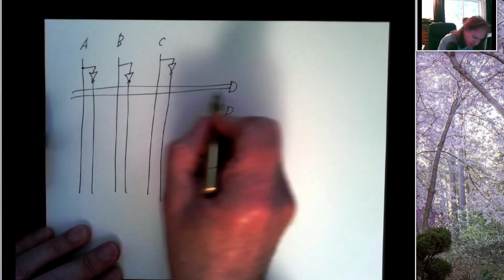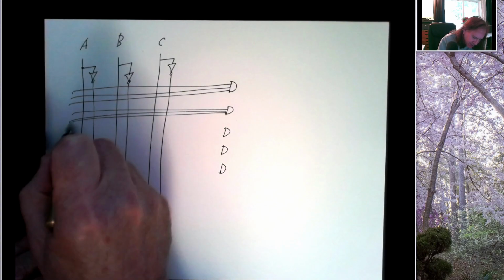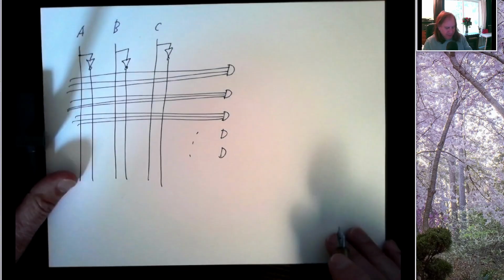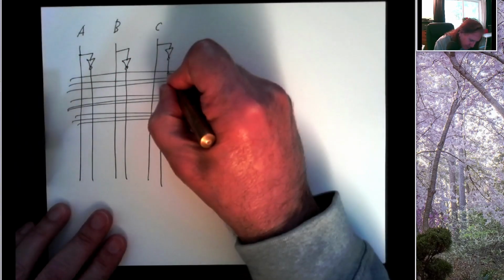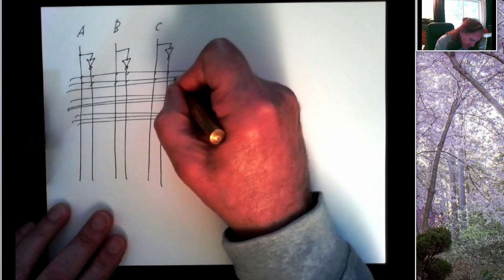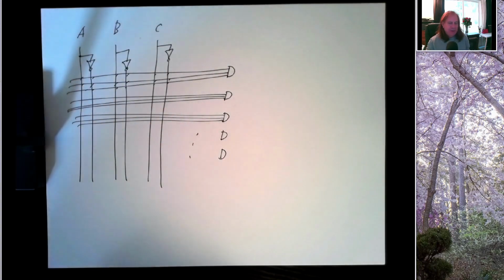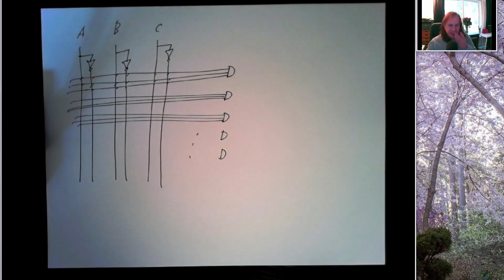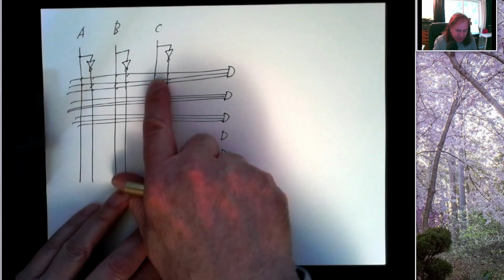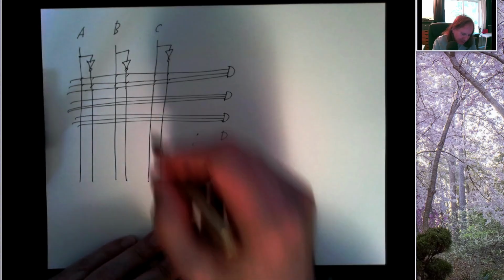So imagine a system like this. We have our usual set of inputs. We have some AND gates. We have 3 wires going to each of these AND gates, and so on. And we have a little fuse connecting each of these junctions. So every one of these junctions has a fuse, and so on. And now we have the option of going into this device somehow and picking individual fuses and saying, I want to run a bunch of current through that for just a moment. And we run enough current through to break this connection.